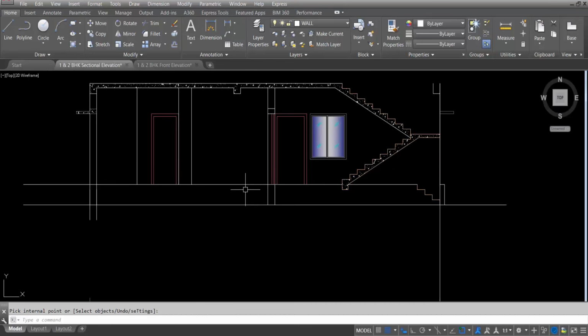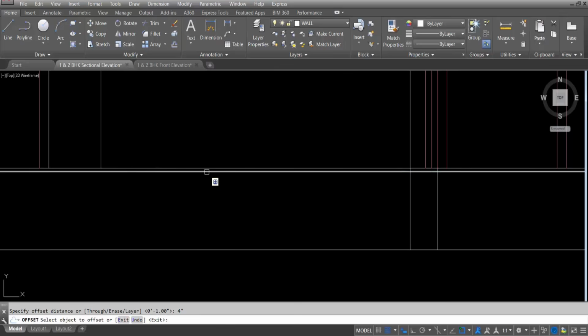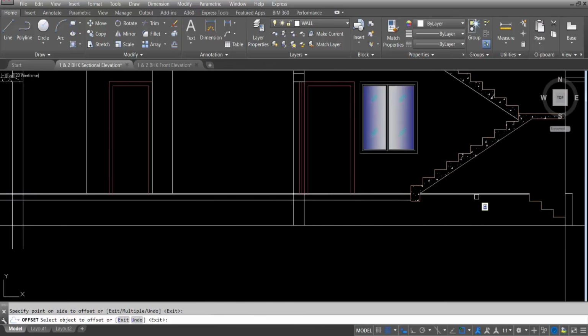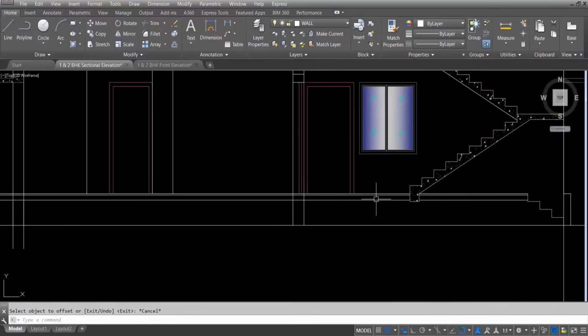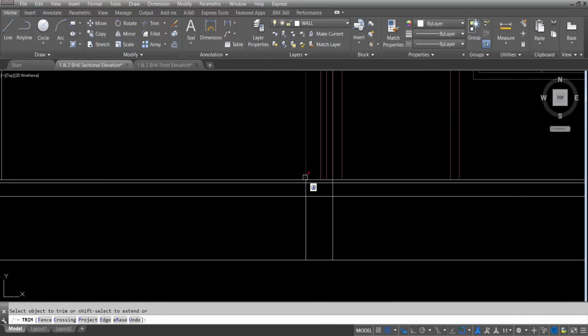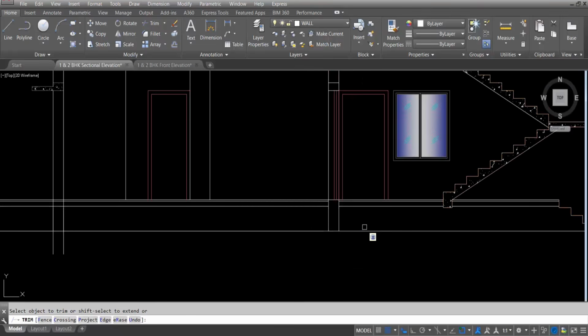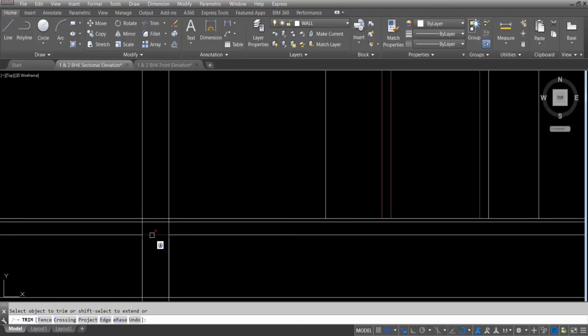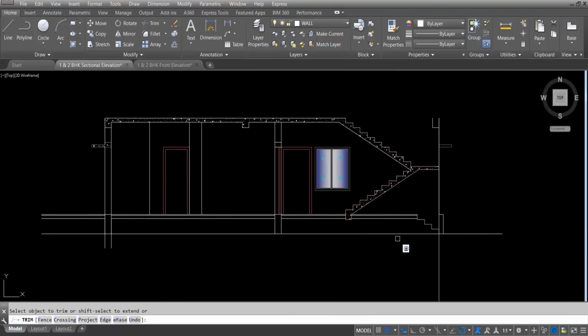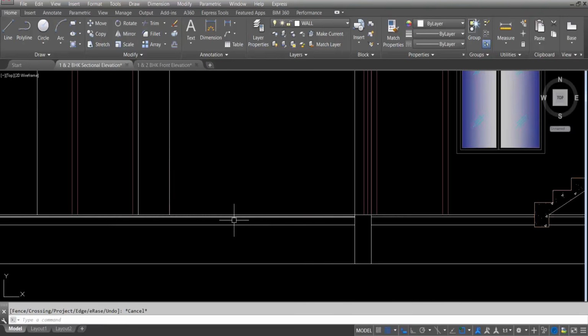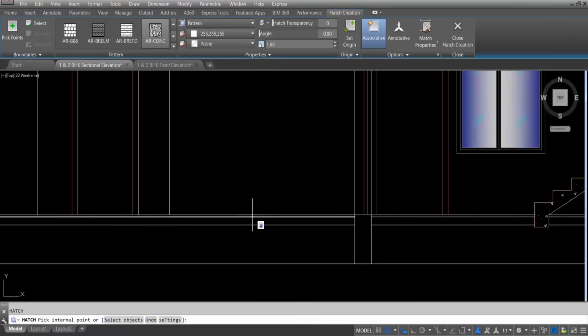So now we have to provide the foundation. So give offset distance first 1 inch. Tile or marble, if you are providing, then we have to give again a 4 inch offset. Select, click here and click here. RCC you have to provide. Okay. So if you are providing marble or tile and plain cement concrete, also you have to show here 4 inch thick.